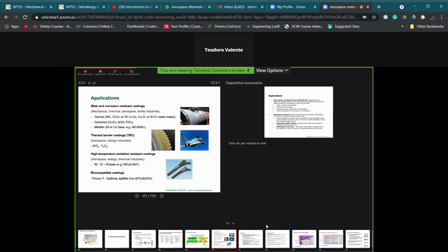But we can also have high temperature resistant corrosion coatings fabricated by these technologies, essentially against oxidation phenomena, which are in this case metallic based, and which are essentially those we have already seen used for the fabrication of the bond coat in thermal barrier coatings, that is nickel, cobalt, chromium, aluminium, yttrium based metallic powders.